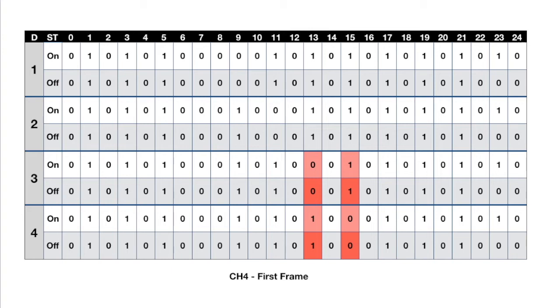So this indicates, in the end, that this is probably a very simple circuit inside of the receiver, right? We have 4 lines coming out of the decoder, and each of these lines corresponds directly to bits 9, 11, 13, and 15 in order to select each one of the devices.